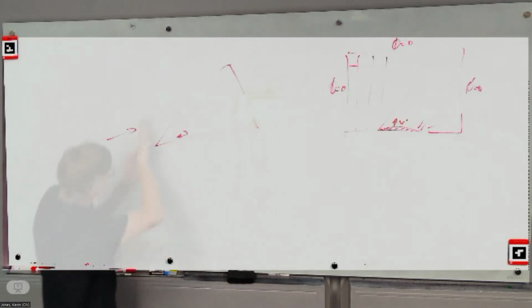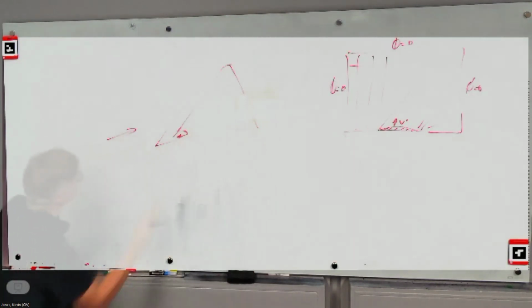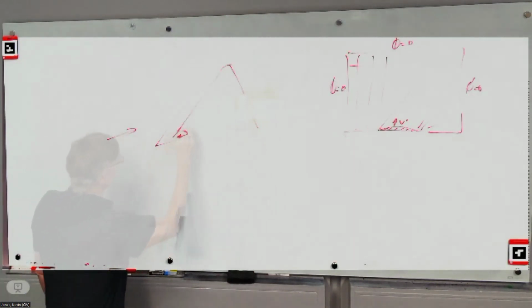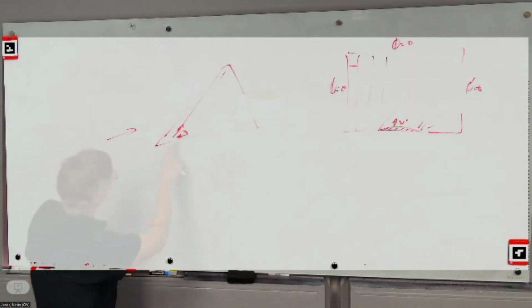And if the wing sweeps far enough, there's really sort of a vortex filament that goes through there, and you actually get flow that goes in that direction. So this vortex actually gets quite strong as it goes outward.